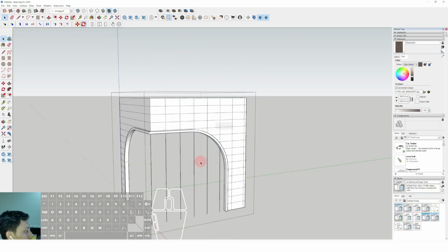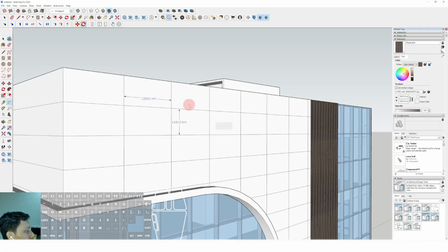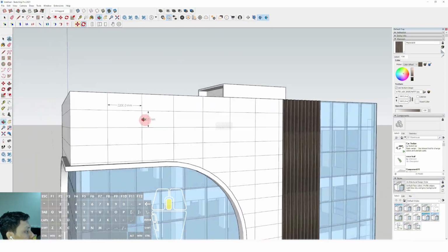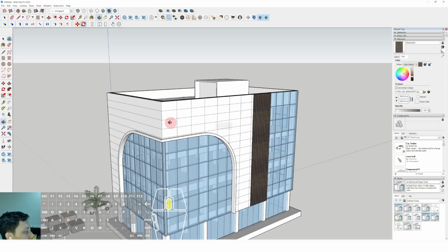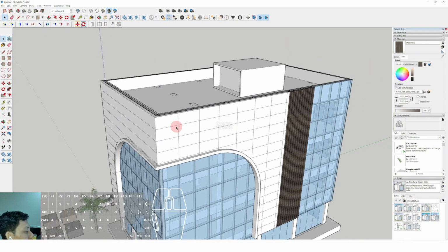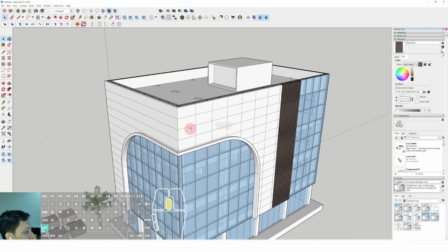So this is about the aluminum composite panel anyway. This is aluminum composite panel arrangement. So this is the dimension for every single panel, 1.1 and 2.2, but the factory dimension of this panel is 2.4 and 1.2 meter. So the extension of every single panel is to be a connector between every single panel in here.